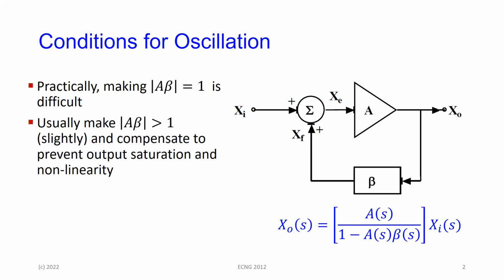and you could draw a simple block diagram like that. The loop gain A beta, the magnitude of the loop gain is 1, and the phase change of the feedback system, in order to have positive feedback, any phase change must be a multiple of 2 pi. It ideally should be 0 or a multiple of 2 pi.